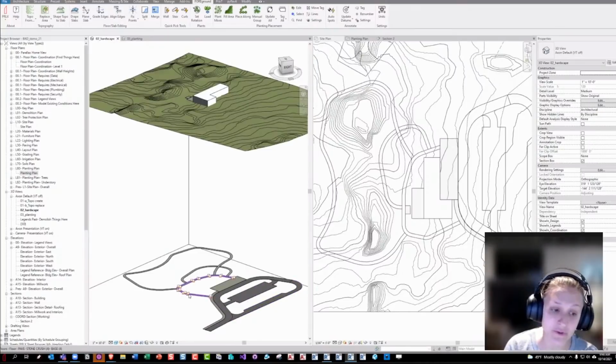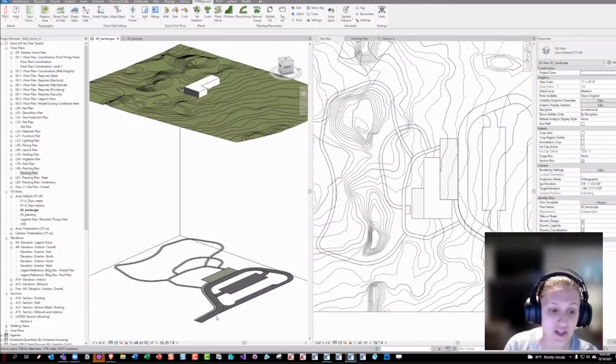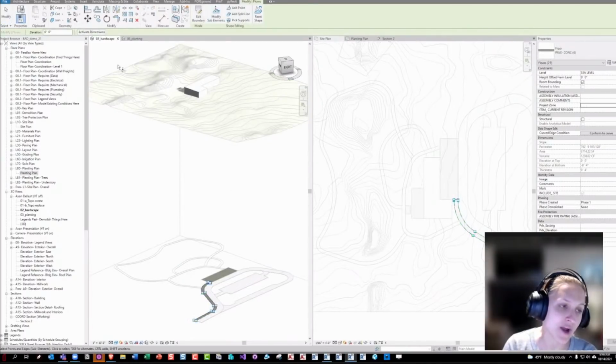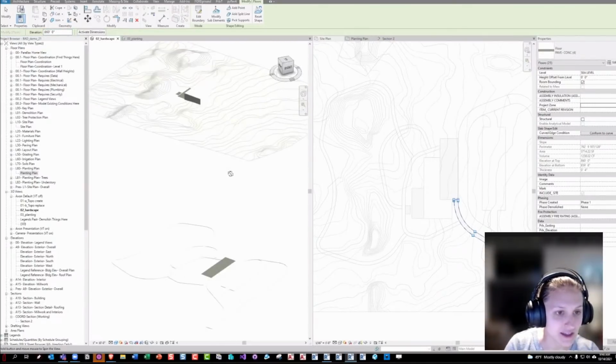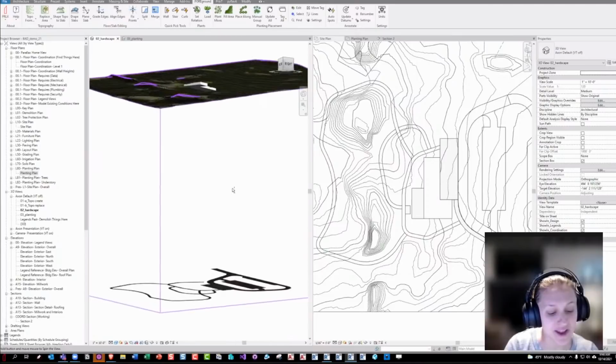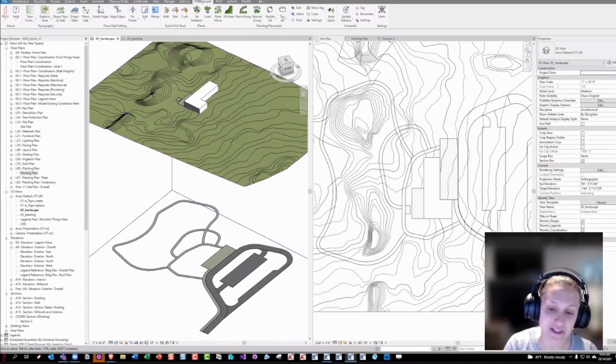So the old school method is basically you have these floors and then you just have to shape edit them manually, which is how I started out doing it. It works. It's just kind of super slow and can be super painful. Essentially, you go into modify sub elements. You can grab them all to speed things up. I can set the elevation of those, and they're up there somewhere. But you can see it's a super tedious process.